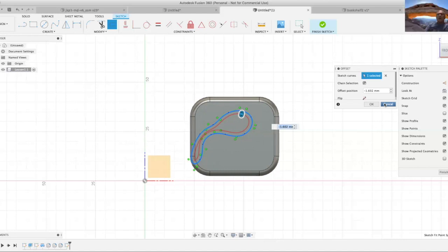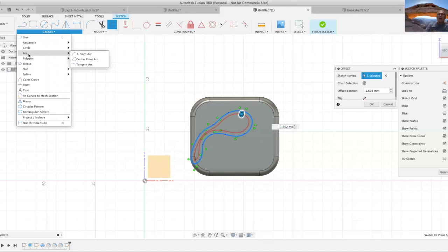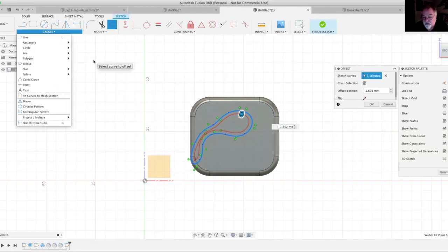Thanks. So the recommendation there, Mark, was using 3-point curves rather than splines because they are less prone to causing complications. Well, an arc only goes one direction, right? Where a spline can go multiple directions. So you'd have to make a series of 3-point arcs, and you can get them to follow just about any canvas you bring in. But I've been making some parts that have complex angles, and the spline, I could never get it to offset correctly.